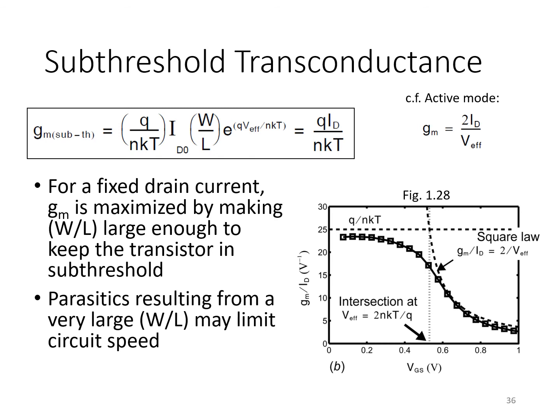We've been showing lots of these plots throughout this video, where we plot very simple currents and voltages while we sweep certain voltages in the transistor biasing and maintain others constant. These are very useful simulations to do when you're just starting analog design with some MOSFETs because, first of all, they allow you to validate the models that you're using.